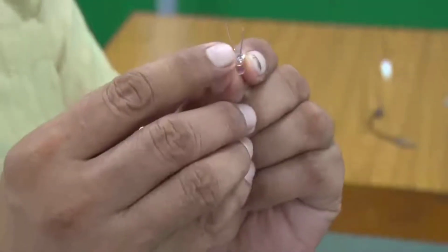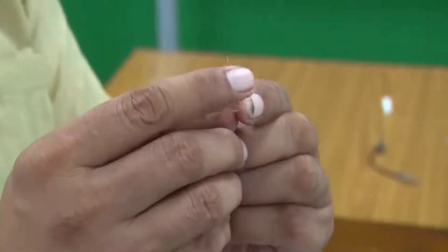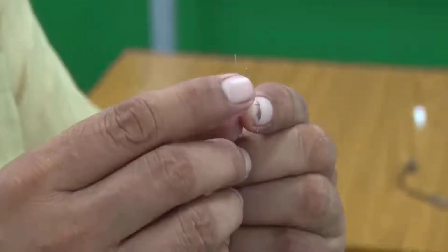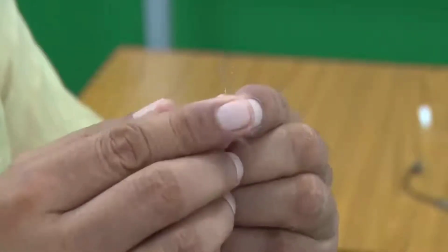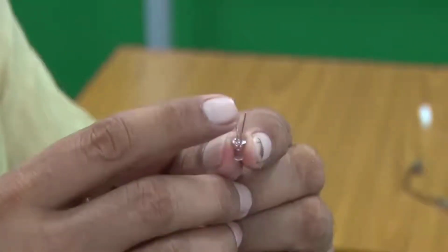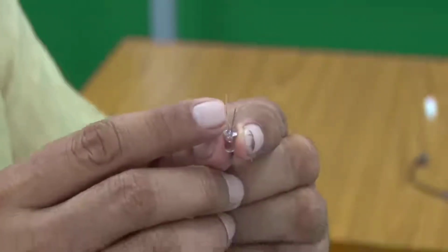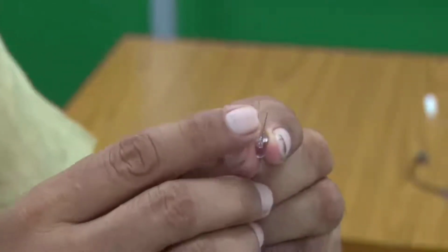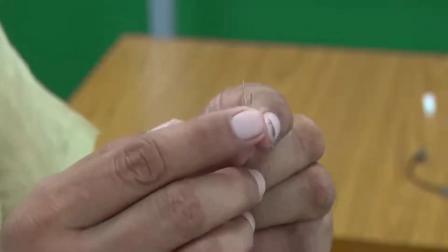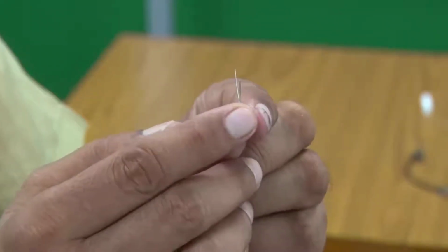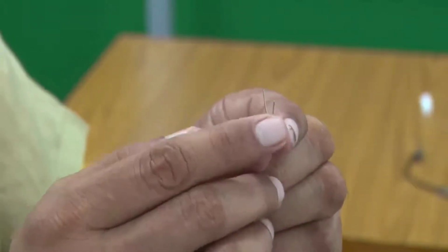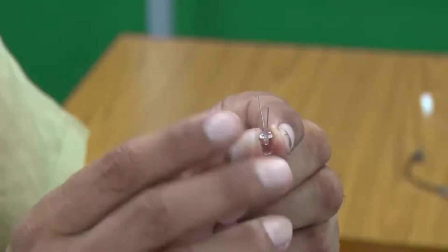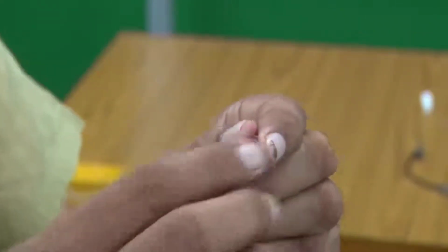The sizes of these two wires, as you can see, are different. One is shorter, one is longer. This tells us that the longer one is to be connected at the higher voltage side, and the shorter one to the lower voltage side, for forward biasing. So, this is the P side and this is the N side. Let us connect this, supply some voltage and see what happens.